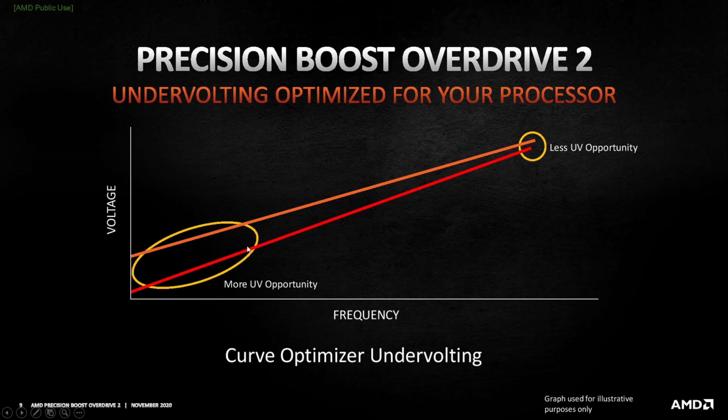a lower voltage. But this tuning has to be done in increments so that you can identify instabilities when they occur and roll back the changes. You can't hit it with a single high value. So you need to increase the offset by 5. The offset goes from 0 to 30, and between these two values the voltage will differ from 0 to 150 millivolts. So it will be controlled like that.